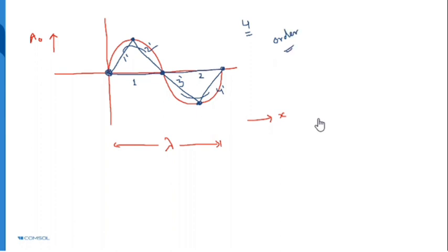So these are linear elements, but if I make the elements quadratic, it will introduce one more node at the center of these elements like this. And now these elements can get bent. If you remember, I told you initially that if you have linear elements, you have one bending like this and like this.